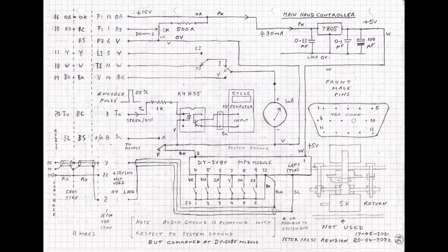The gear ratio and tender wheel diameter result in an effective wheel circumference of 55 mm. Entering this value into the cycle computer gives the correct scaling. I was surprised that the cycle computer could accept such a low value. The computer was then set to give results in kilometers per hour and kilometers distance, which gave more resolution than MPH. At 10 kilometers per hour, the encoder's single pulse frequency works out as 50 Hz.